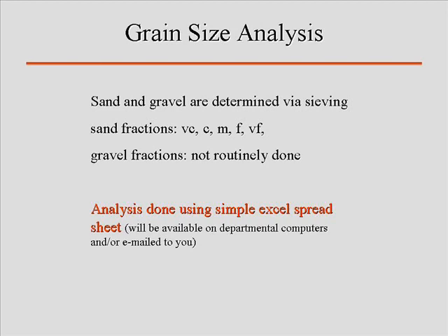The other thing I don't like about the hydrometer method, never have, is I don't think the hydrometer method is particularly accurate. Now, those of you that did this before, you know, when you put the hydrometer in, you've got to read the scale. Well, for accuracy, you should be getting to 1/10 of a division, but you can't read any closer than about half. And there are times, I swear to God, the density's gone up after a while, and if you put that into programs, the density goes up, it just throws everything out. So you have to fudge your data to get it to work, and everyone's done that.